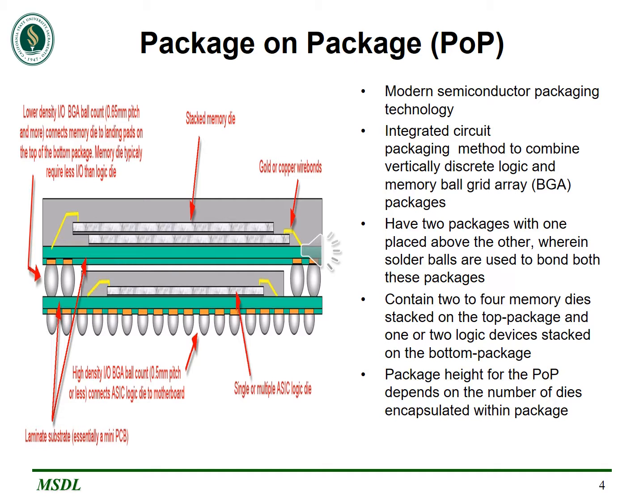It is a modern integrated circuit packaging method to vertically combine discrete logic devices and memory ball grid array packages. In this, two or more packages are installed atop each other with a standard interface to route signals between those packages. This structure allows higher component density in devices such as mobile phones, personal digital assistants, and digital cameras.